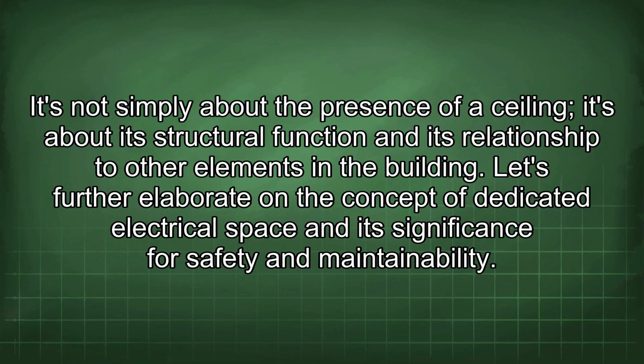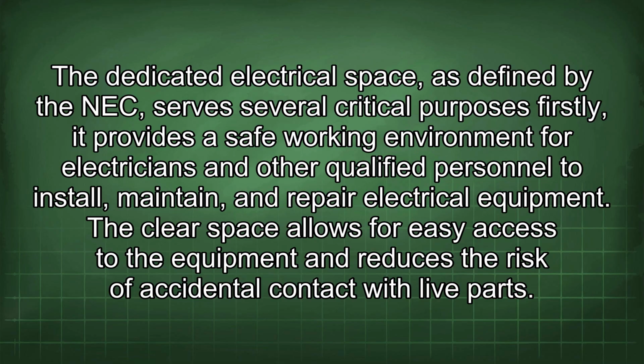Let's further elaborate on the concept of dedicated electrical space and its significance for safety and maintainability. A dedicated electrical space, as defined by the NEC, serves several critical purposes. Firstly, it provides a safe working environment for electricians and other qualified personnel to install, maintain, and repair electrical equipment. The clear space allows for easy access to the equipment and reduces the risk of accidental contact with live parts.